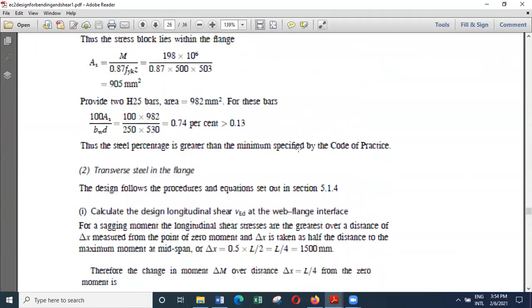And also when it comes to inverted T-type foundation, if you do a model with springs, then you can always find the bending moment diagram. When you know the bending moment diagram, you can find the location of zero moment and the maximum moment.